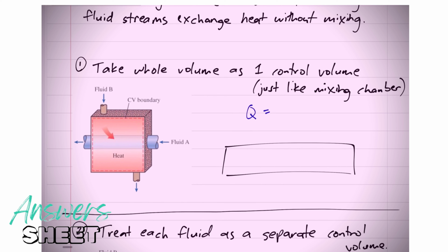The heat transfer is internal, so it is 0, and it's just what we got: m dot out, h out equals summation of m dot in, h in. So that might be an equation to use. That might be helpful for us to use.